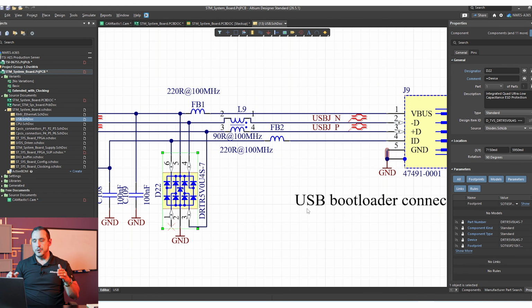And these components need to be selected carefully because they are being put on high-speed data lines. Basically, when we put an EMI filtering component or a TVS diode or any other circuit protection on data lines for digital signals, we want to make sure that those components don't impact or filter out any of the digital signal content that you're trying to transfer along those lines.